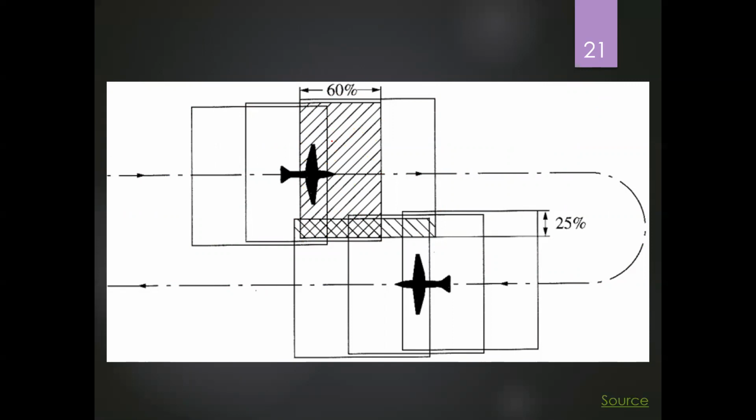If this image is damaged, then you have no information about the damaged area, which is bad. So we always want to make sure that one area is scanned at least 2 times, which means there must be overlap.